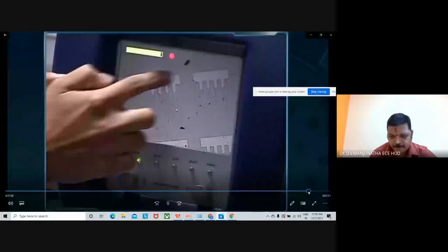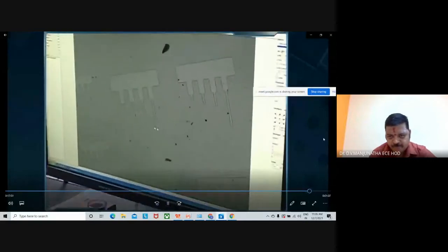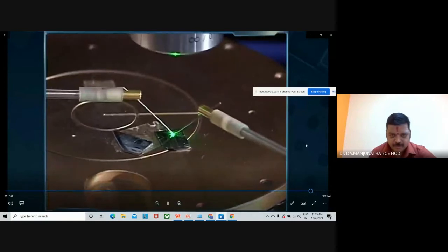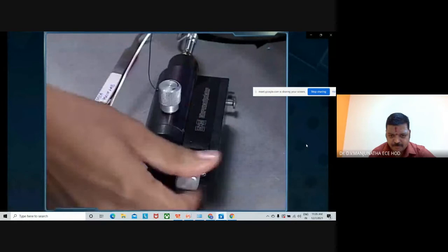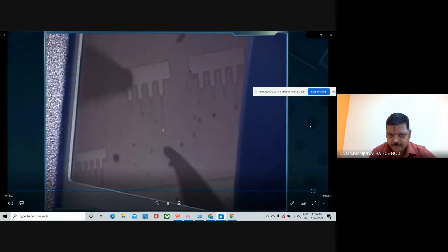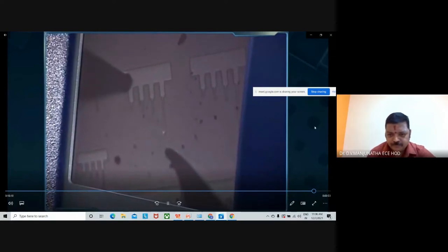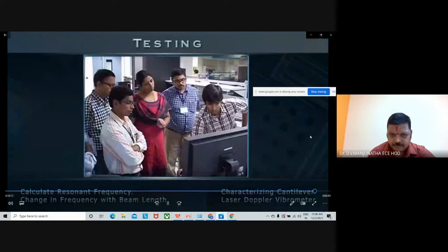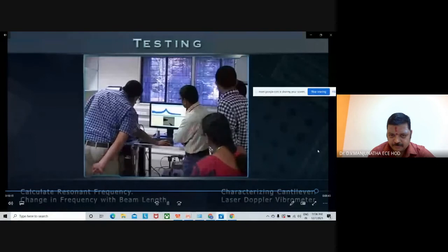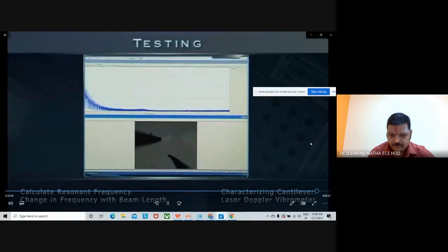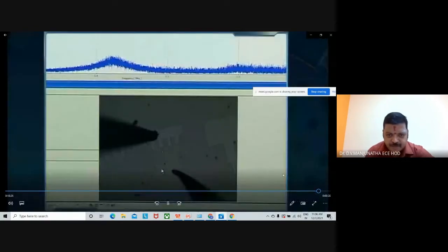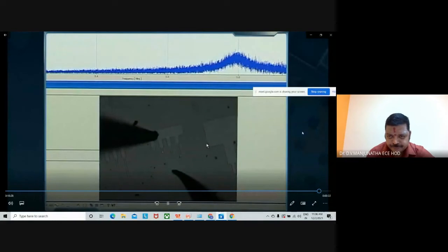There is software to analyze vibration data. After placing the sample on the vibrometer, we position the probes to make contact with the cantilever's handle and the beam anchor in the device layer. Then we apply a specified voltage and observe the frequency response of the vibrating cantilever beams. The vibrometer picks up resonant frequencies of the fabricated cantilevers and displays corresponding velocity peaks.